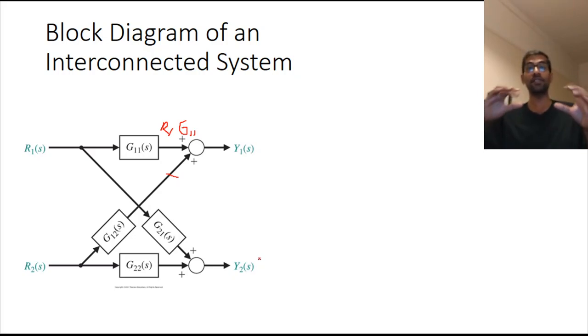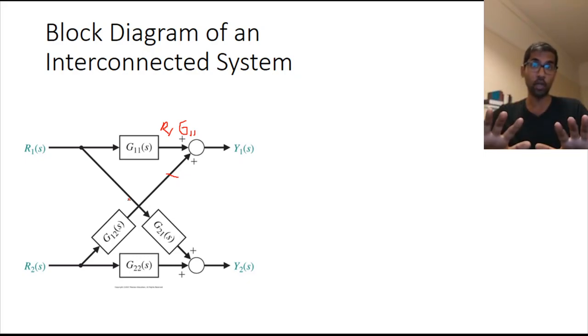And so basically what we have done is we have modeled a complicated system and we have broken down that complicated system into small physical systems. And then for each physical system, we have found out the transfer functions. And then we connect them and put them together as shown in this diagram. And then we can relate the input of that complicated system with the output of that complicated system. Okay, so we have drawn a block diagram and we have reduced the block diagram to get the transfer function of that block diagram.